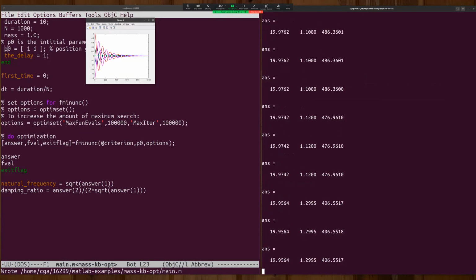I started at a position gain of 20. It's sitting there at 19.9. It's getting the damping up to 2.2. So it's very slowly improving things. You see it plotting the 5 trajectories. Okay, we're getting there. Damping's up to 4.8. So we almost got the damping where we want it.